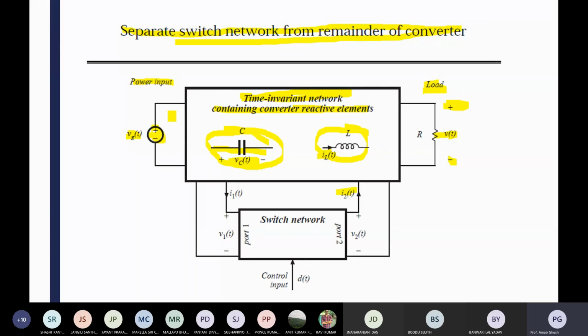So your controller is there, and there is a boost converter. The input of that boost converter is directly connected to the solar panel; the voltage and current come from the solar panel. The output side of the boost converter is connected to a capacitor through the DC bus. Now, how would you control the switching pulse of the boost converter? If you go for the maximum power point, you have to analyze this.